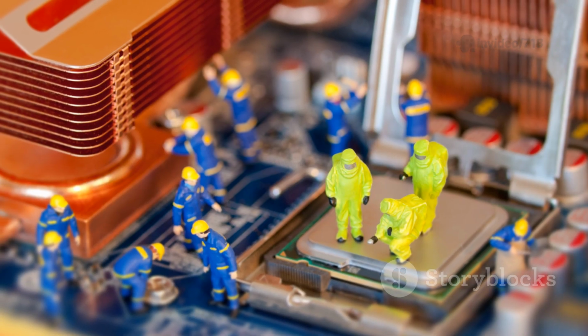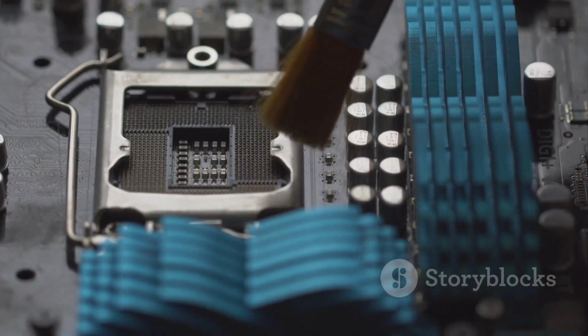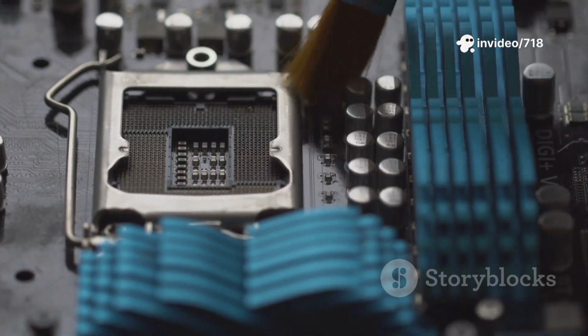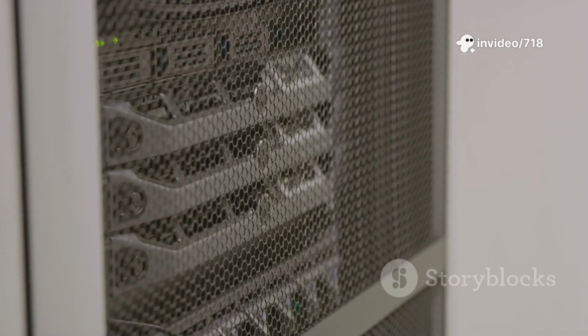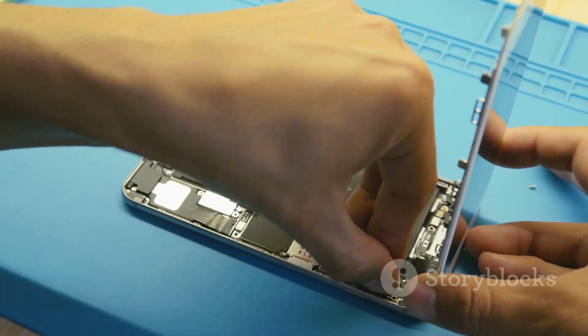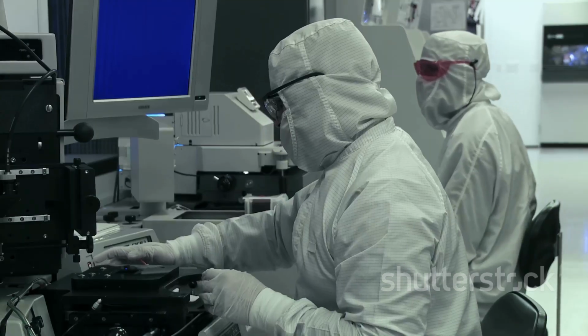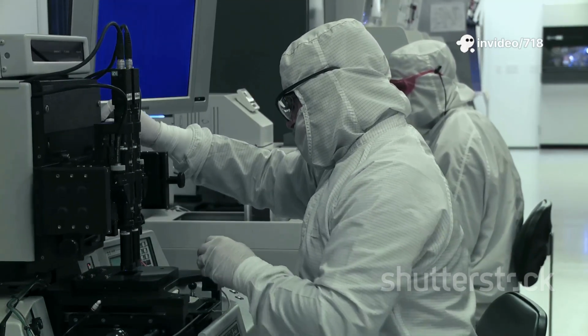To handle this, the memory controller periodically pauses whatever it's doing and systematically goes through every single row on the chip, one by one, and performs a refresh cycle. It reads the data and writes it back, not because the CPU asked for it, but just to top up the charge and prevent data loss. This relentless background refresh cycle is the true price of DRAM's simple design and high capacity.